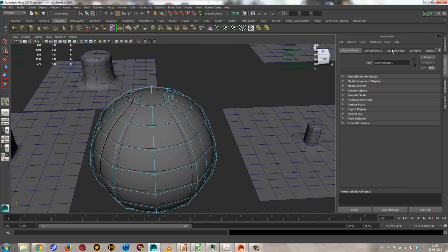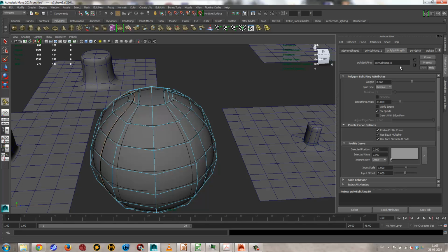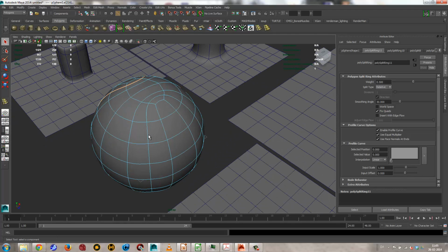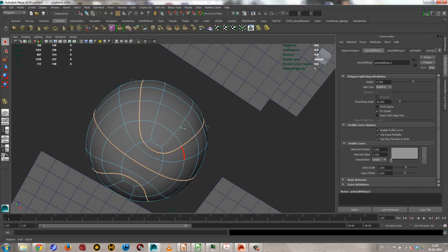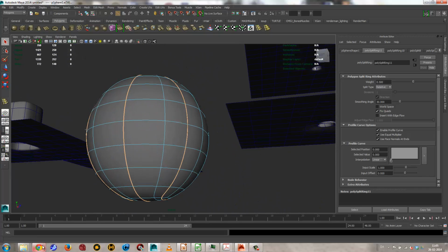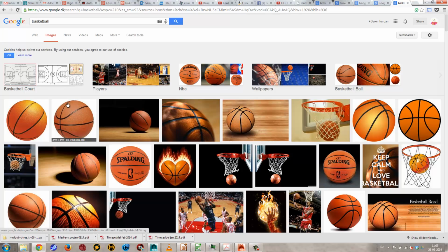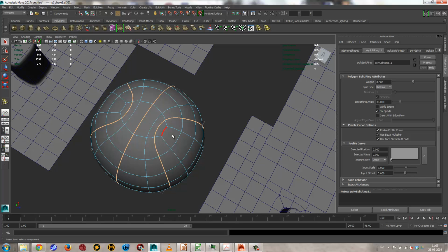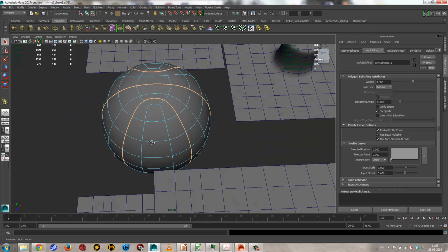and you can see I have my poly split ring over here, and I just set these to 0.5. That means in the middle for both of them. Okay, so what I want to do is I want to use this edge here and this edge here and this edge. I actually have a dead vertex in here. I'll just fix that in a second, and let's just have a look. And then I need the line going the other direction, so I need one line going through here. I don't have that at the moment. I need to add that.